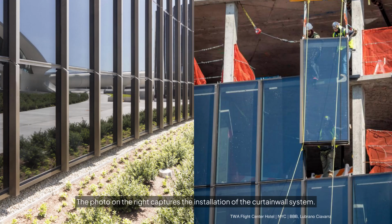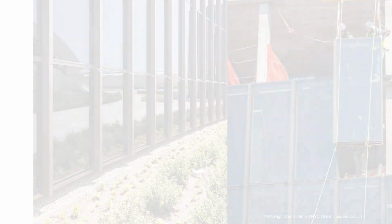The photo on the right captures the installation of the curtain wall system. The prefabricated curtain wall units are assembled in a controlled factory environment and then hoisted into place, hung from face-mounted anchor brackets. This off-site prefabrication approach enables faster construction timelines while improving quality control, which in turn enhances performance, weather resistance, and craftsmanship on-site.